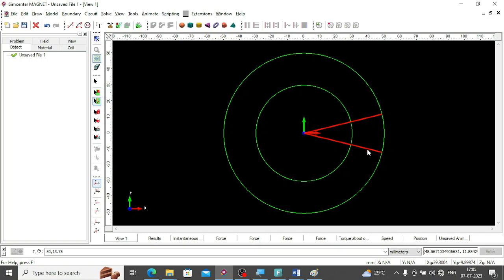If I need to select this line, I have to select the construction line, and then click on the lines. By holding control, you can select multiple lines. Once you select the line, you can use segment edges. If you are not selecting any line, segment edges, which you can see at the top, is not enabled. Once you select the line, segment edges will be enabled. You can click on that and delete the excess lines present when you drew.